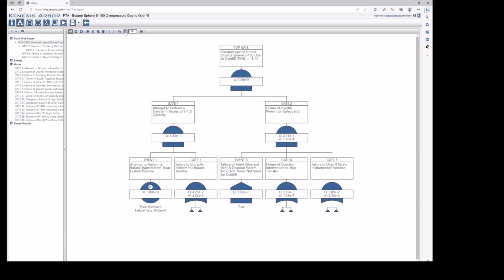So this is the top line, if you want to think of it that way. On the left is the initiating event. On the right is the failure of the protection layers, if you will. And granted, down at the bottom, there's a bunch of shared stuff back and forth. But ultimately we said we have a target maximum event likelihood of 1 in 10,000 chance per year.